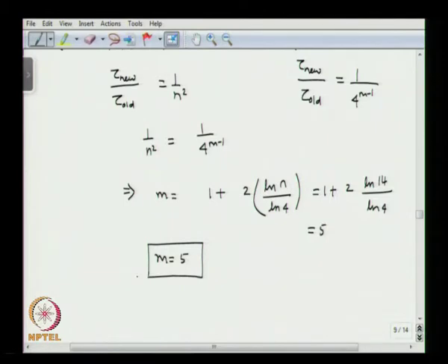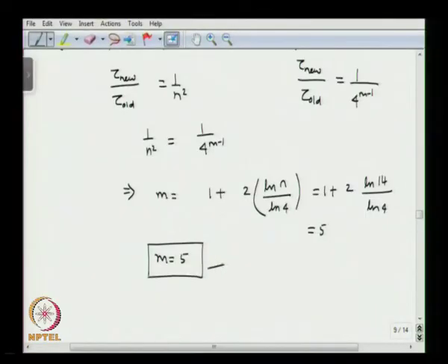So what we saw is that if instead of going for parallel lamination layers, in which case we would require 14 different parallel lamination layers, if we go for sequential lamination we can do it with 5 different stages. Okay. So only 5 stages are required in sequential lamination.